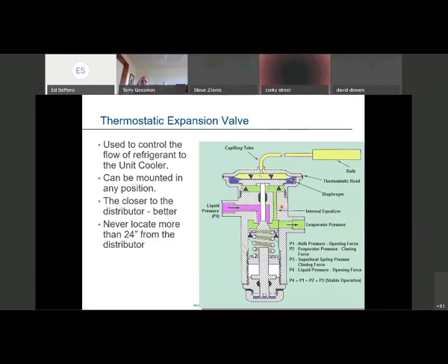Well, obviously you're going to have some pressure drop, but I'm including the fact that we don't have a distributor or distributor nozzles. A pressure drop of really anywhere from 1 to 3 pounds across the evaporator, this type of internal equalized expansion valve would work just fine.